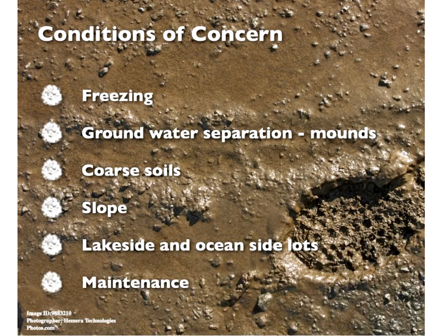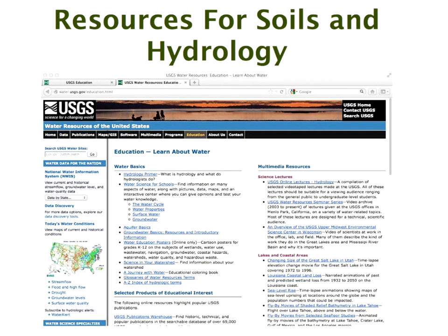Okay, what you've got to worry about: freezing, which we spoke about; groundwater separation. Are you going to put in a mound in order to get adequate groundwater separation? Very coarse soils, as well, of course, as very heavy soils, the slope, lakeside and oceanside lots, and maintenance. And we'll talk about these as we go.